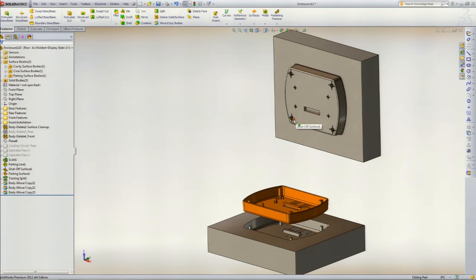Any questions on that? Okay, good. Oh, yes? Shrink for my material? Yes, it was the beginning step where I took the plastic part and enlarged it by a factor of 0.03 of an inch per inch overall. So that was taken care of.